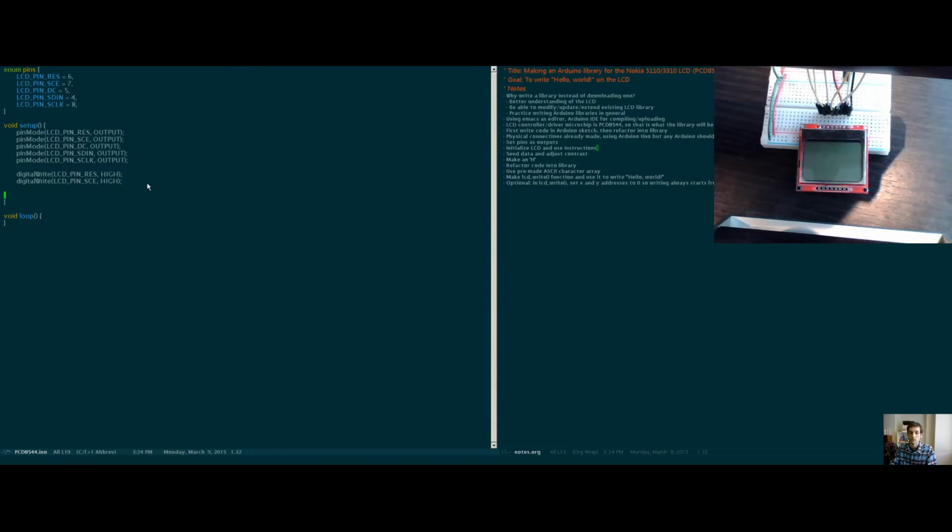So we're starting our LCD initialization. Initialize the LCD. And we're going to start with the reset pulse for the reset function. So we take it low, and we delay 1 microsecond, and we leave it high again. So that's our reset pulse. And after that,